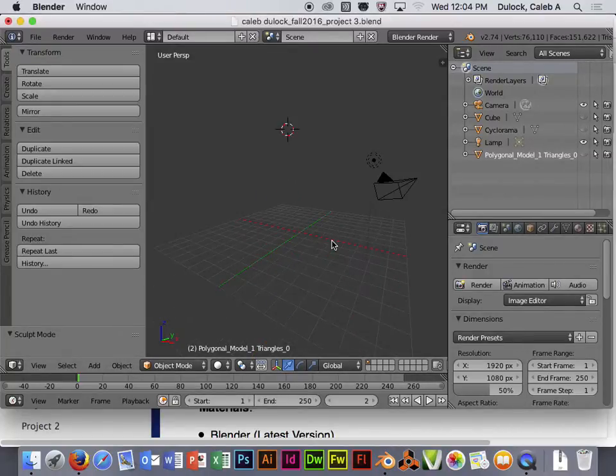And I'm going to recenter my view a little bit. Again, if you're trying to recenter your view, you can hold down Shift or Control to pan your screen around to recenter your floor image, the floor grid on screen, so that you can kind of see it. And then you can use pan and tilt orbit features with your number pad keys, as long as your mouse is hovering over your viewport when you're doing that stuff.